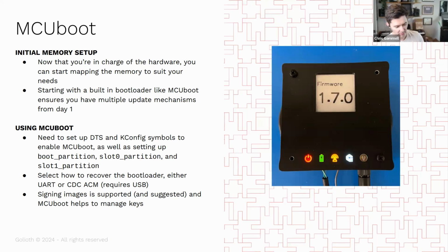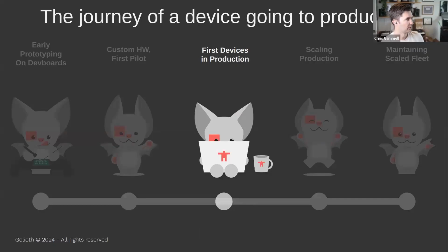MCUboot is my go-to when I'm using Zephyr, again because I'm usually starting from projects that are based on MCUboot. You can also start signing keys and having more security baked in. We'll talk about security a little bit later. But also, I talked about blowing stuff up and being able to recover from that, being able to recover from hard memory errors and being able to get back to the bootloader and load new images in. Very, very important from my perspective. Keep losing my mouse, sorry. All right, so definitely not all-inclusive there.